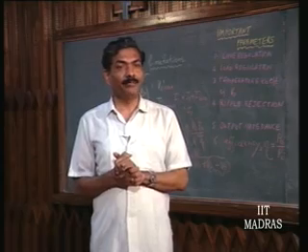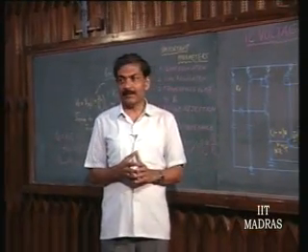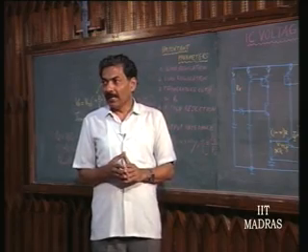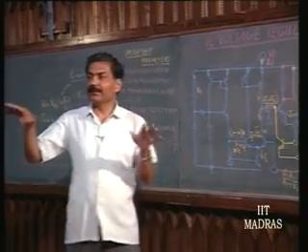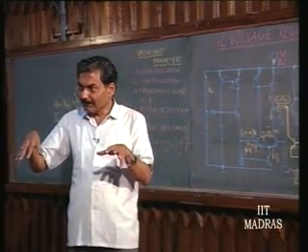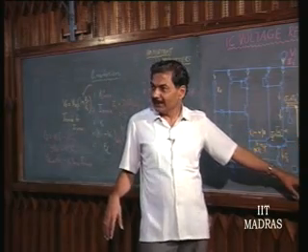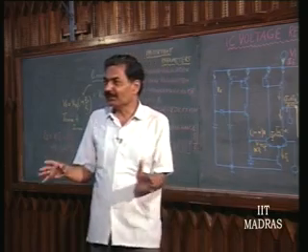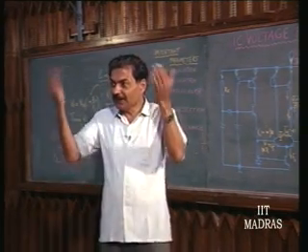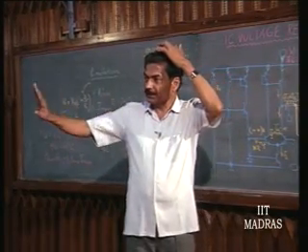This particular thing is very important because after you do this design and come up with Vi max and Vi minimum etc., and then you start meddling with the circuit again, these things will again change. You will start meddling with the circuit particularly to provide protection for the circuit. At that point of time you should not forget about these limitations, and again these limitations will now change once all this protection circuitry comes into picture, that we will discuss separately.